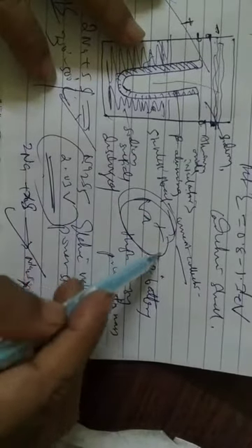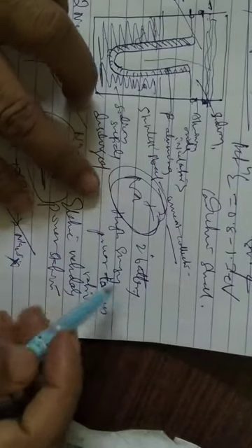So this is the reaction and its applications: the anode, the cathode, what they are used for, and how they are separated by beta alumina. The conduction is only because of the movement of Na+ ions. It is a very good secondary battery with a high energy power to mass ratio, giving 2.03 volts. That's why it is used in most electric vehicles and other applications.